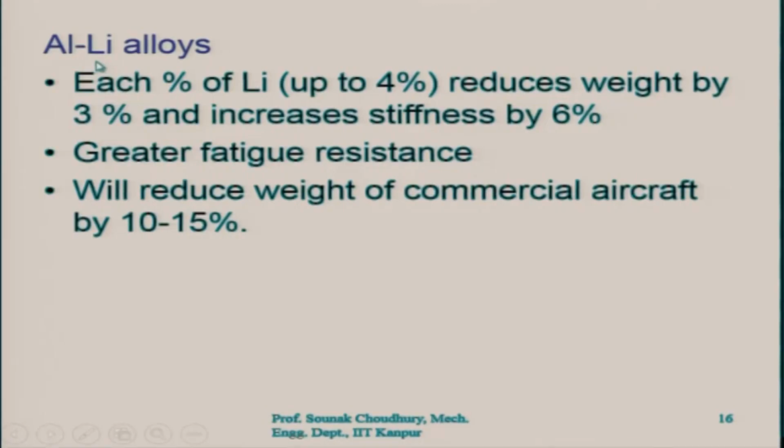Now, aluminum lithium alloys, for example, each percentage of lithium, by the way, up to 4%, reduces weight by 3% and increases stiffness by 6%. These are experimental results, and you can see the effect. This is a drastic reduction in the weight, by the way, and it increases the stiffness by 6%.